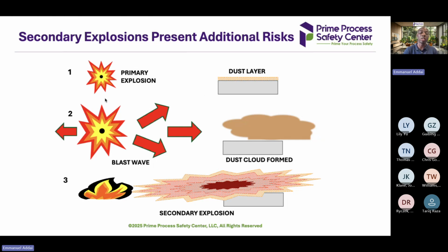So there's also another scenario which is very, very problematic in the industry. And I think that caused the total destruction of the Imperial Sugar, which is dust accumulation and also secondary explosion. Secondary explosion results when there is an initial explosion. You have dust accumulation on various equipment such as surfaces, or maybe on the side of the equipment and the ceilings. And the initiation pressure from the first explosion automatically is going to shake the system, and the system is now going to create a dense dust cloud. And since from the first explosion you already have your combustion operation, the heat automatically is going to ignite the dust cloud which is being generated from shaking of the system. You're going to have a secondary explosion.